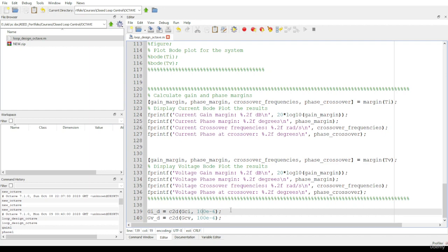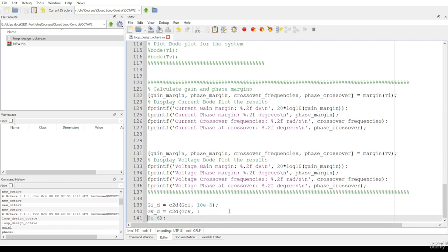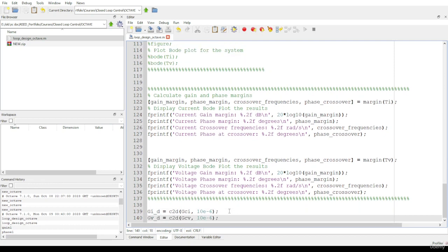So if you're implementing the closed loop controller code every 100 microseconds, then this is perfect. If you're implementing it every 10 microseconds, you change that time to 10 microseconds. Of course, if it's 20, you change that as follows, etc. It's 100 microseconds in this case, and I'm just going to leave it at that.